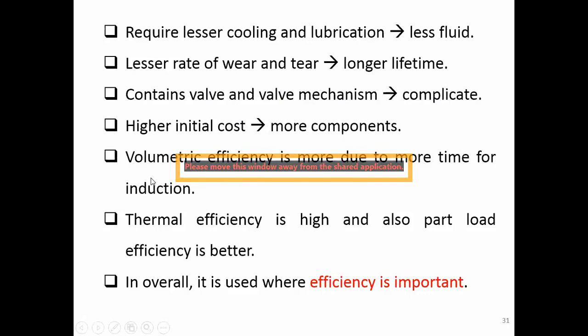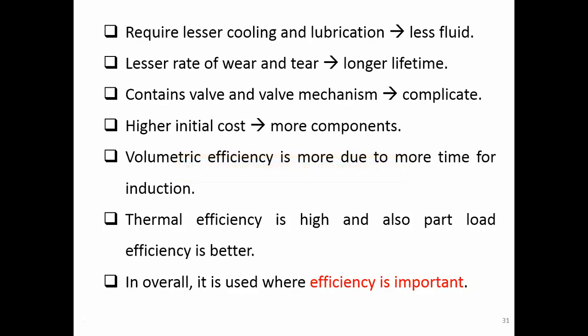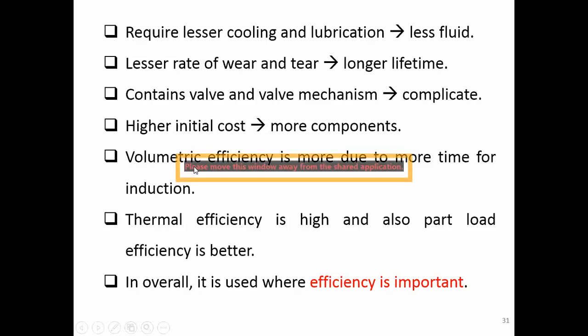They have a full intake stroke to draw the air or the air-fuel mixture into the cylinder, right? This will make the volumetric efficiency higher. And that means the thermal efficiency is higher as well, right? And as a result, the part load efficiency is also better.